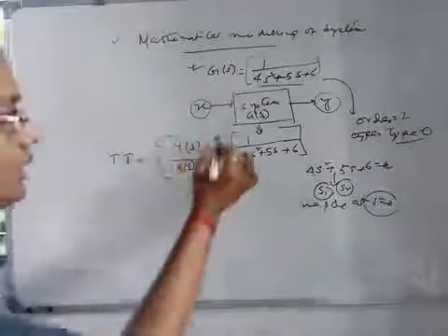Now, if this voltage is applied, that is, if this is your forcing function, then what will happen? How to solve this problem? First of all, consider, for example, i(t) is the amount of current passing through it. As you see, R and L are connected in series. So i(t) flows through R, and also through L. Now, we may want to get the voltage across the inductor, which we denote as v0(t).